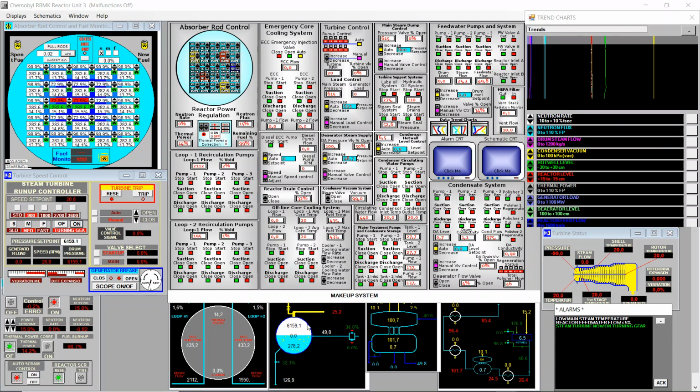Okay, we're at 6000. We are very close to the pressure. We need to start turning the turbine. When we start rotating the turbine, we'll need to look a lot at this turbine status. This will give information about the vibration, differential expansion, temperatures of the rotor, stator, etc.